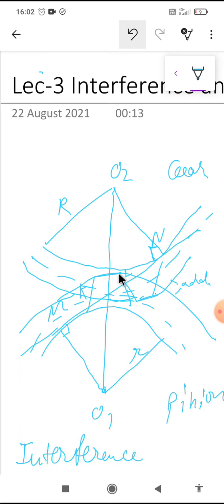So when this happens, it is called interference and occurs when the teeth are being cut. When they cut each other, material will be removed, or the metal to metal contact is so hard that it will cut each other. In brief, the phenomenon where the tip of the tooth undercuts the root on its mating gear is known as interference.